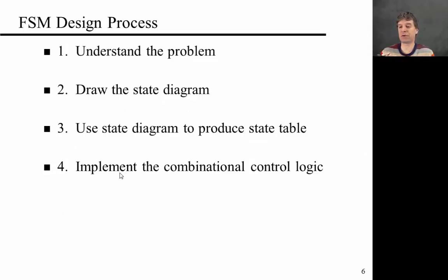So going forward, a lot of what you're going to do in this class is essentially design various types of finite state machines. And this can be broken down in a few steps, and really only the first step is hard, namely understanding the problem, right? If I ask you to design a traffic light controller, you have to figure out how to translate that request of build something that determines how the lights should switch to a state diagram. Once you have the state diagram, you can draw that. That's relatively straightforward, and everything becomes very automated.